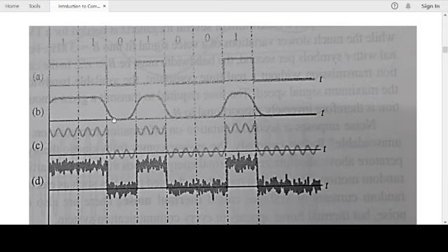This is known as inter-symbol interference. The symbol from this portion 1 has spread over to this 0. The signal from 0, which was supposed to be 0 up till here, has started to move to 1. If the symbol width is very small and there is a very rapid change of ones and zeros, then these things are smeared, they are not so distinct.